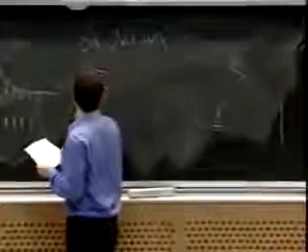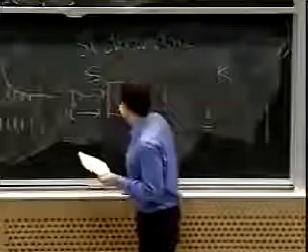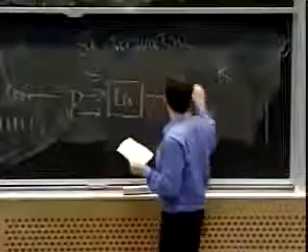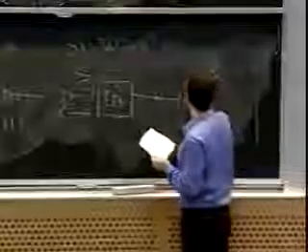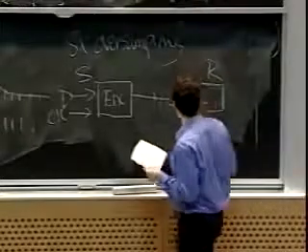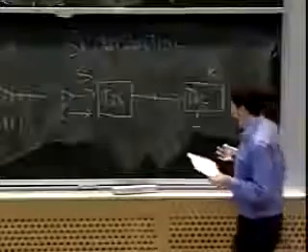The idea is simply as follows. You have some data at the sender and a clock at the sender. Those go into some encoder box. They're transmitted out over a line to the receiver, which has a decoder box. But the decoder box needs a clock signal that's been lined up with the sender's clock signal.